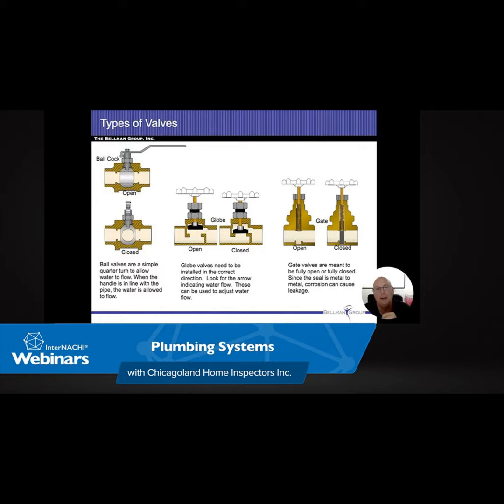You want to be careful that you're not going to kill the bacteria in the toilet. So we come out of the house, we go into the septic pit. From the septic pit, it's going to have those different baffles in there, and that's where the cleaning is going to happen. Then the effluent, or the liquid, is going to start going out into our leach field. Typically, those are 2 to 3 feet deep. As we come out of that catch basin, that's that big rectangle at the top, it's going to go through a distribution box.